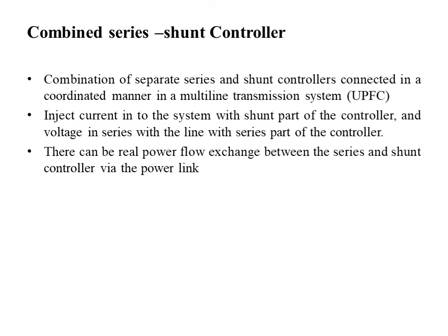But if I want to have control between these two controllers, the one connected in the upper line and the one in the lower line, I want to control both controllers at a time, and I can use a power link. By using the power link, we can have power exchange between the series controllers connected in both transmission lines, as well as series and shunt connected controllers in both transmission lines. So by using a power link, we can have control between the controllers themselves.